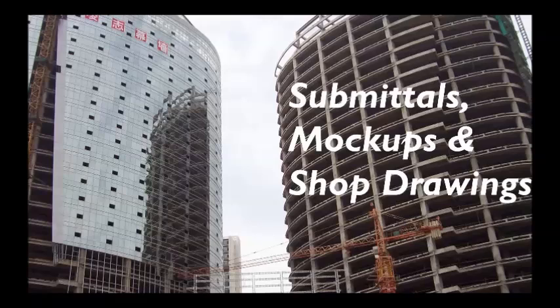And then there are shop drawings. Shop drawings are usually drawings that a fabricator or manufacturer draws based on the architect's drawings. But they'll do their own drawings because sometimes their manufacturing processes or the way that they detail things might be slightly different than what the architect had asked for, and they'll send the shop drawings back and say things like, this happens on cabinets, where they'll say, okay, you drew these cabinets this way, and based on the joinery that we make or the way that we manufacture these cabinets, we're going to have to do them slightly differently, but are you okay with this?